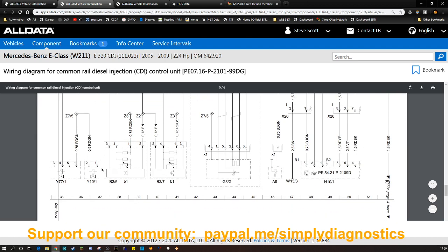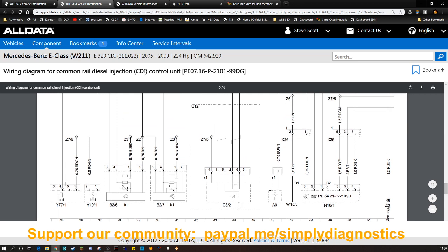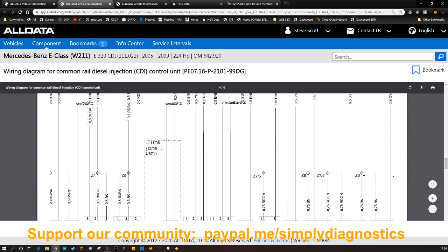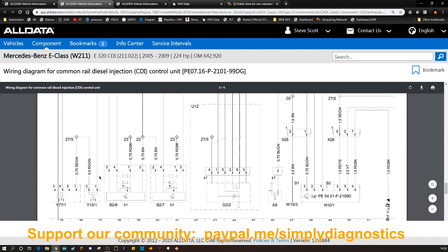Yeah, so what does that tell us? You can see there's no wire going to pin 5 and no wire going to pin 3. So this is probably going to be a 3-pin connector, or a 5-pin with only 3 pins connected. So one is going to be a voltage reference, isn't it? And that one is going to be a ground.